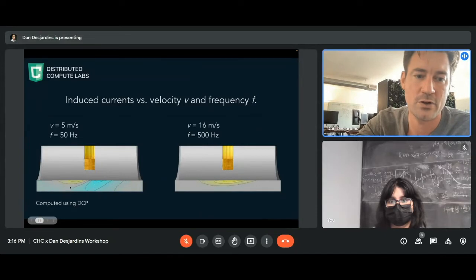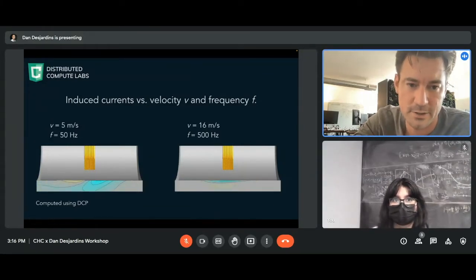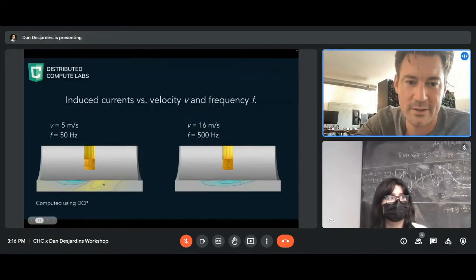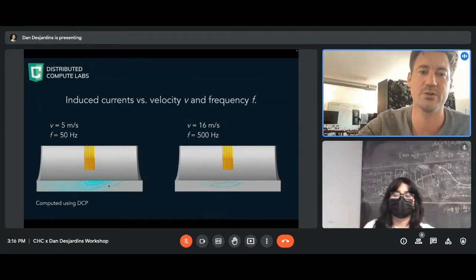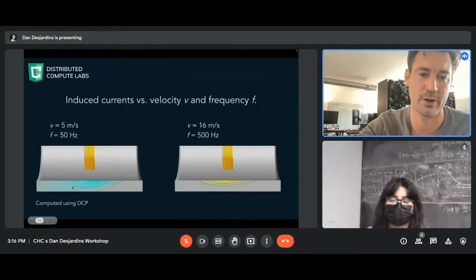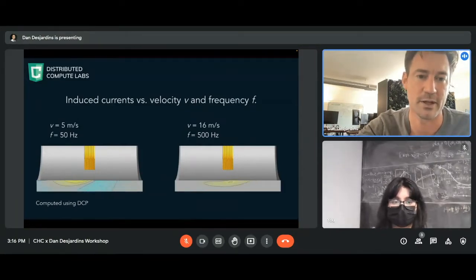So in a higher drag scenario, as the coil turns on the field in a certain direction, it's inducing a cushion of currents. And it's obviously moving, that's why there's a lot of asymmetry. But then these currents, the wake, is weirdly migrating to become a bow shock, and it sort of comes around like this, right? So there's a recirculation vortex of the induced current densities. Now yellow is going into the board, so to speak, and blue is coming out of the board, and they're reversing like in and out because the current is going in and out, right?